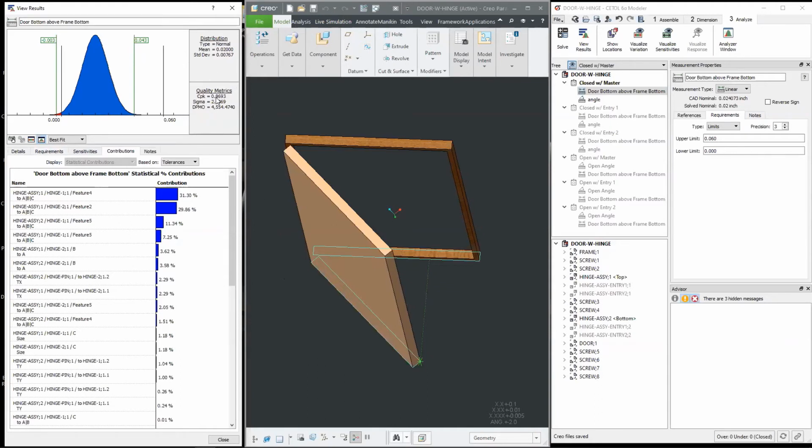So we're dealing with a CPK of 0.8. Obviously, we're not centered, so we might have some room for improvement from making a nominal design change to move this distribution to the right. And we've got some other characteristics here. The one I'm going to focus in on is comparing the standard deviation of all of these, because this is a measure of the width of the variation, right? So it's kind of the worst case.